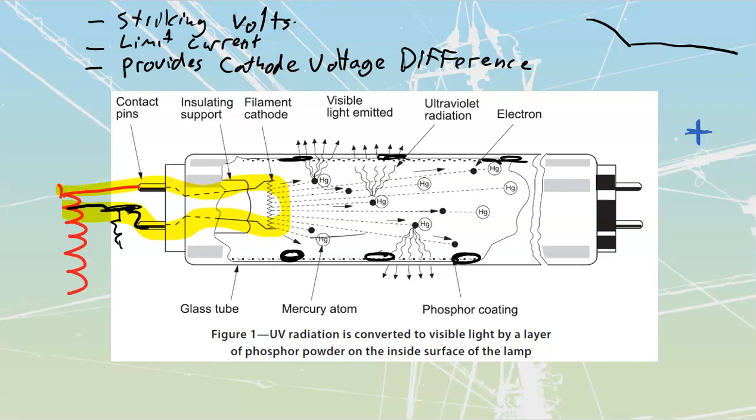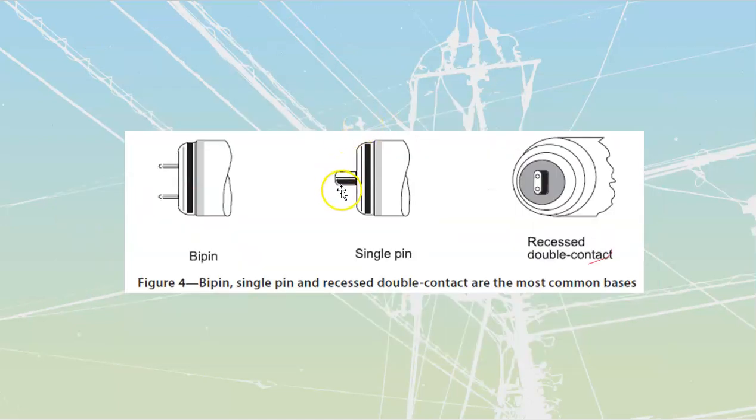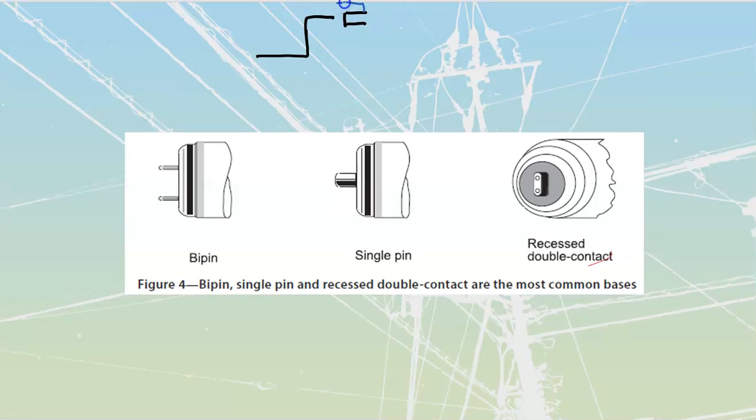They also talk about the slimline. Slimline is just a name for the ones that have the single pin end. These ones over here. They're an instant start lamp with a single pin at each end. That instant start lamp operates at ridiculously high values of voltage, and there should be a switch where your power comes into one of those tombstones at the end. That's going to be a spring-loaded tombstone, so here's the cup that the pin goes into, and if I draw this,